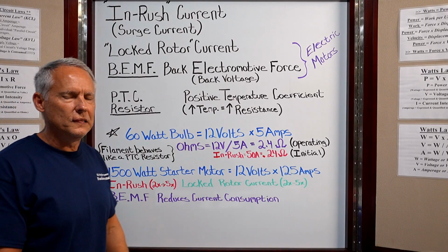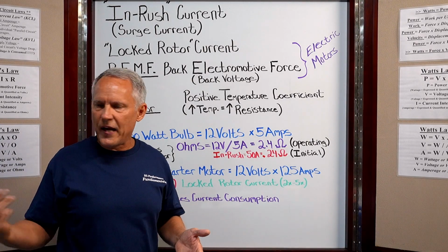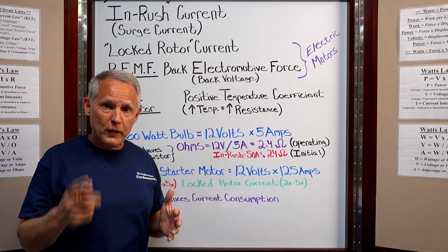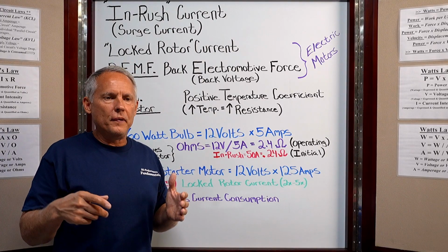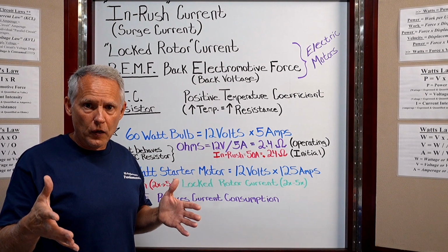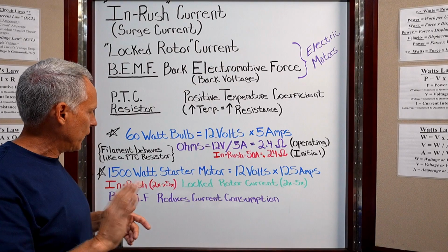What that means is that as that electric motor is turning, that starter motor or fan motor or whatever motor it is, once it gets up and starts rotating, as it speeds up, it starts to generate its own voltage. It starts to act like a generator and actually produces its own current and voltage. So they call that back electromotive force.